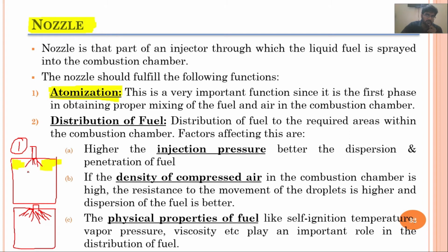Since fuel is not sprayed properly, the fuel is in the form of maybe some drops as well. It will penetrate across this dense air and will come in contact with the air which is at the bottom, and not only that, but it will combust with that air as well.